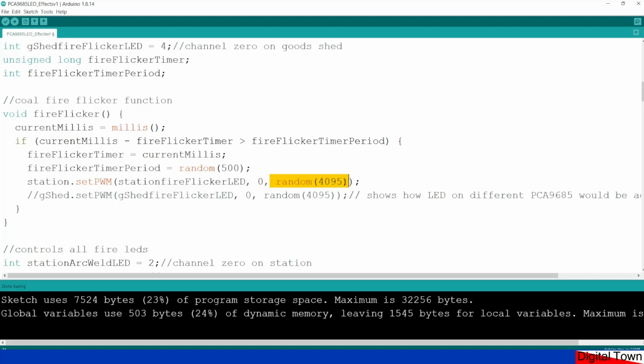Now I've done a separate tutorial, again there'll be a link to that, but if you're going to start putting delays in your code, basically the Arduino is stopped while it waits for that time period to go by. So if you were waiting using a delay for your fire flicker, then all of a sudden your crossing lights aren't going to be working.